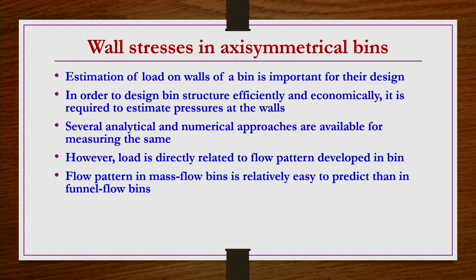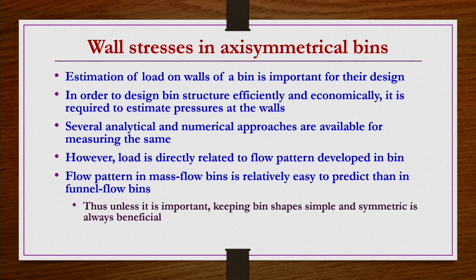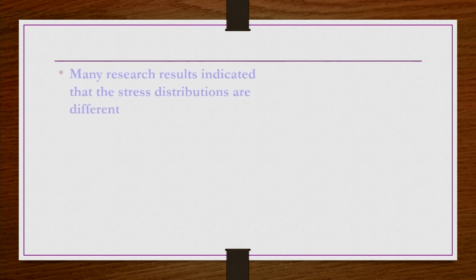Flow pattern in mass flow bins, as we understand, is relatively easy to predict compared to funnel flow bins. Thus, it is important to have simple and symmetric bins rather than chisel shaped bins, etc. So, it is always better to have simple and symmetric hoppers.